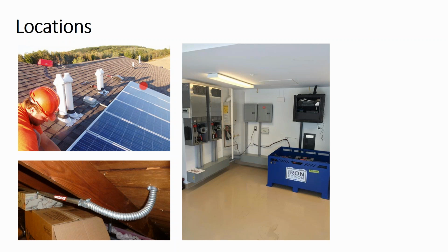And so you might be using wet rated conductors, and you might have a wet rated box, and then in here you might have a dry rated conductor. So do you have to bring the dry conductors up into this box where it's a wet environment, or do you have to continue to use your wet rated conductors all the way onto the first box where you land on? Where is the line between a wet environment and a dry environment?